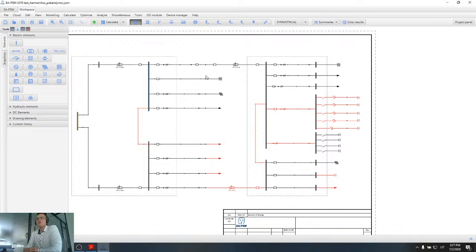So harmonic is the main reason of capacitor and transformer overheating, and overheating causes problems for insulation, and after the insulation wears out, we have a short circuit. And this short circuit is actually the main reason for an explosion. So harmonic is the primary source in most cases, which overheats the equipment and causes problems to insulation. When insulation is damaged due to high temperatures, then we have a short circuit which damages the equipment.